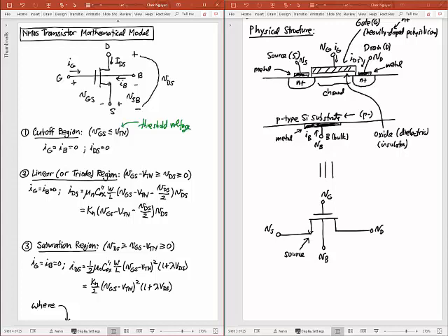And that's often going to be on the order of 0.7 volts, but it actually will change depending on how we've biased this thing up. Okay, but if VGS is less than that threshold voltage, maybe I'll indicate 0.7 volts there, but it's around that. It could be greater than that too. But when I have VGS less than that, no current flows through this device. Okay, so it's just like the transistor we want.